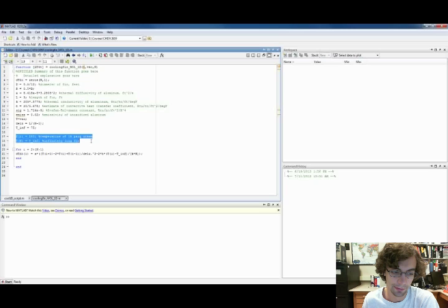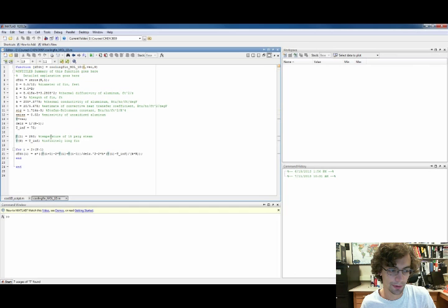You'll need 2 boundary conditions with respect to the z position for all time. The way that we know that is, of course, because we have a second partial derivative of temperature with respect to z, so therefore we need 2 boundary conditions of temperature at a particular z for all time.